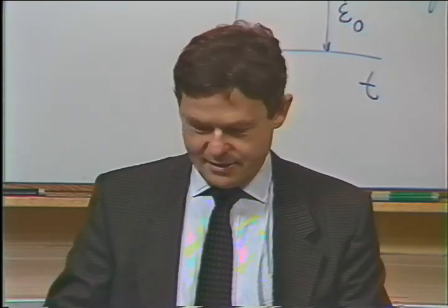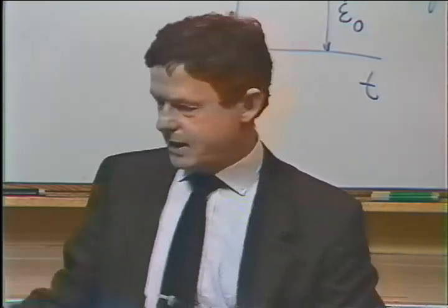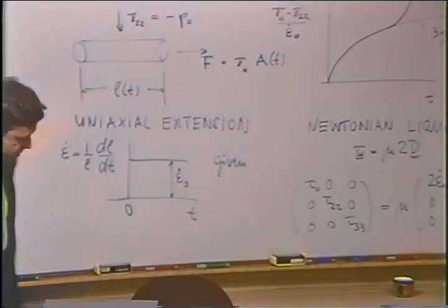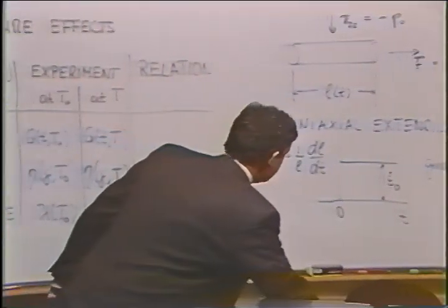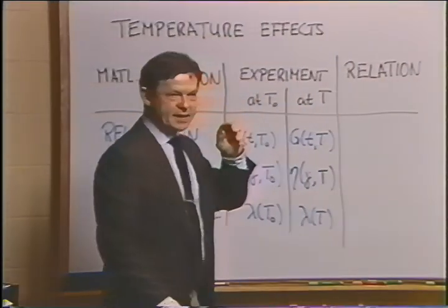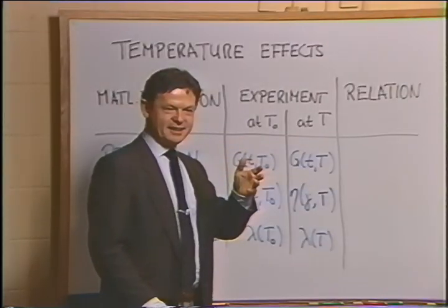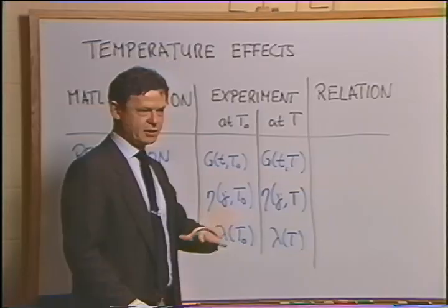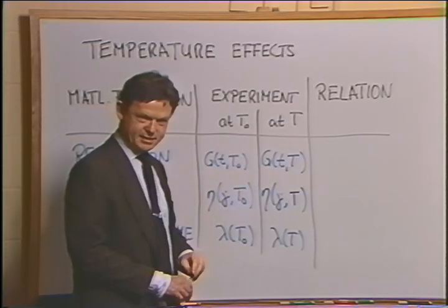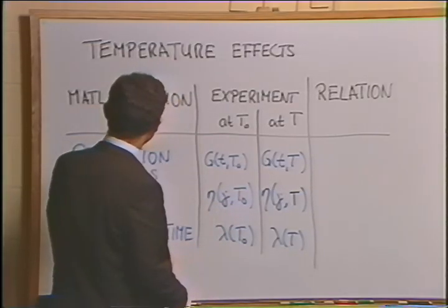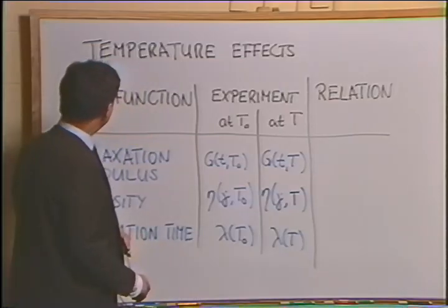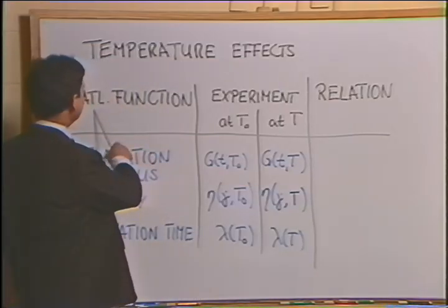The temperature effects are also very interesting. The behavior in shear and extension depends very much on temperature. And we saw that the shifting of the viscosity curves resulted in a master curve. They all could be shifted into a single viscosity curve. And similar temperature effects can be found with various material functions.